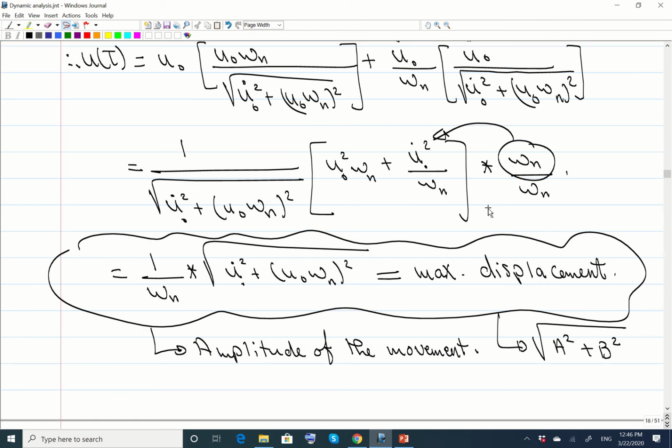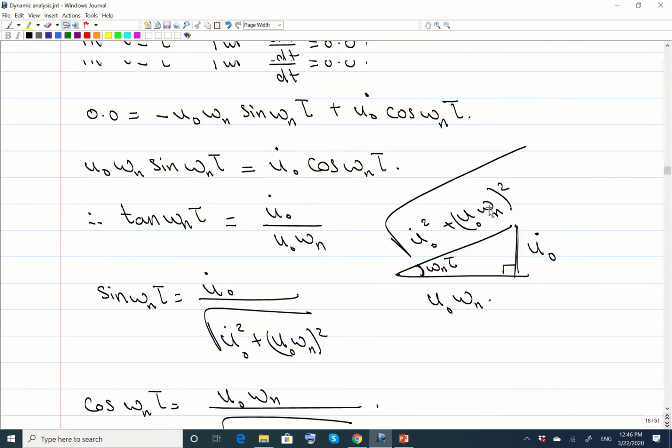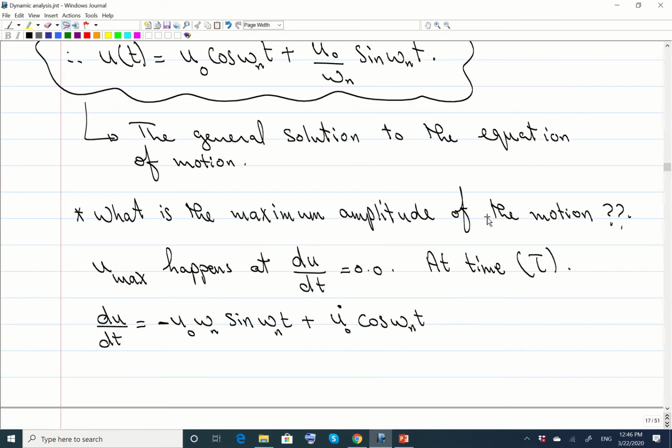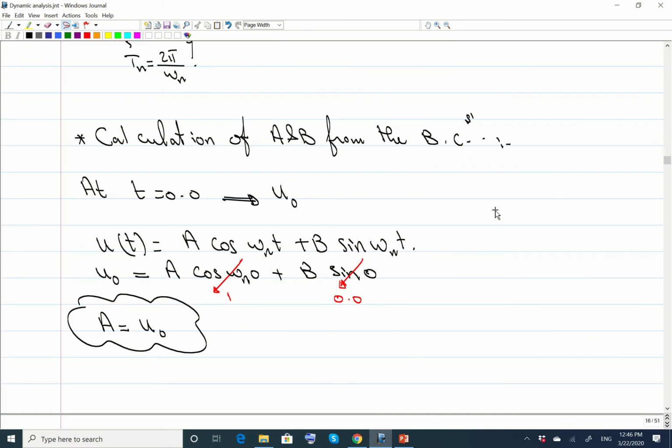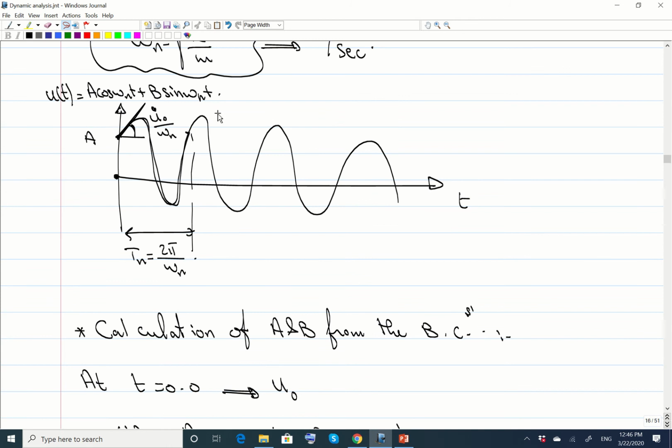Now, another thing that we want to find is the energy during that vibration. We have that frame, or that mass representing the frame. It's vibrating like this. When it's vibrating, there is an energy. How much is the energy during that vibration? At any moment, the energy comes from the kinetic energy, that comes from the velocity of the vibration, and a potential energy. Actually, we're not going to call that a potential energy, we're going to call that the strain energy